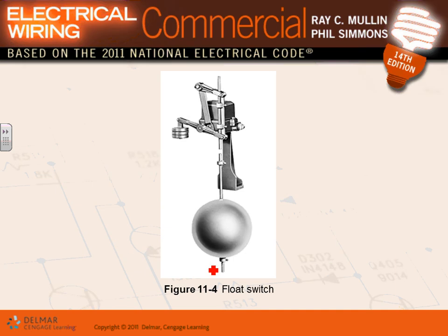Floating switch, you guys, has anybody wired these? You've seen them. The water starts getting up and up here and pushes this baby up. As it pushes, guys, it closes a contact, and now my pump is pumping, right? Then the water starts going down, down, down, and that ball goes down, right? You have to have a range. You allow it to pump all the way until it reaches almost the bottom and stops.